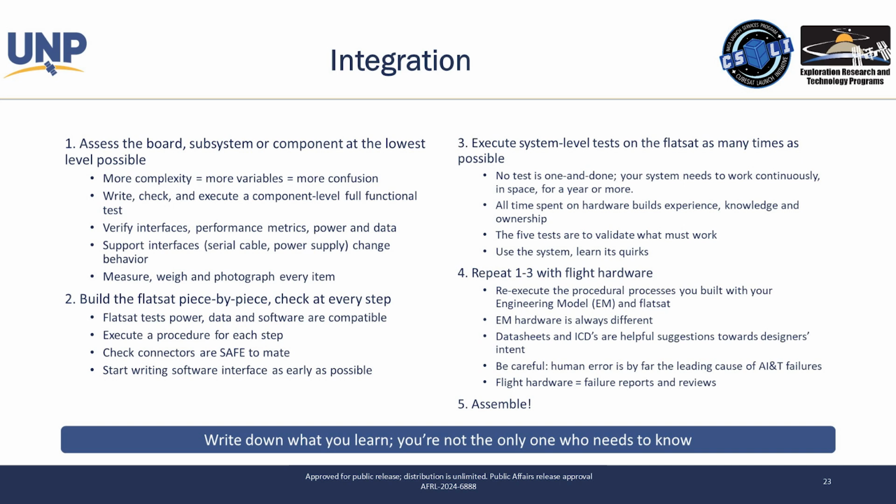Then you build up this flat-sat, integrating those components and subsystems into a larger system, doing that as methodically as possible. Scientific method: never change two variables and remeasure, only change one variable at a time. That way you know what's actually causing the change in the outcome. Spending as much time as you have in your schedule at that flat-sat level is the most important thing of any system component. Like I said, it's so iterative. That takes so much time to learn, iterate, fix, and build. And all that time spent just builds experience, builds knowledge, gives you the best chance of success.